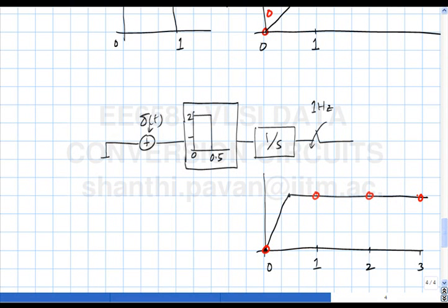So this also represents a delta sigma modulator with a noise transfer function of 1 minus Z inverse. There will be a delay for data also. Wait, 1 minute. Okay, so a critical question is what happens when there is delay in the quantizer. I will come to that. At this point, let's assume that we have ideal quantizers which give you their outputs, whatever, a fraction of a picosecond after they have sampled the input. Does it make sense? Alright.